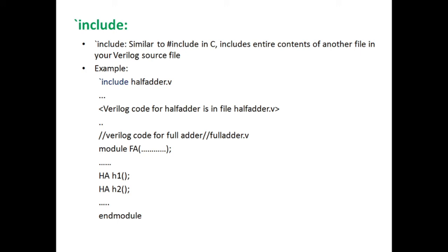Similarly, `include plays a vital role in our Verilog HDL. So I have used `include halfadder.v. Suppose I am going to design module full adder, with a, b, c, s, cout as its ports. The full adder is constructed by instantiating two half adders, HA, one copy is H1 and the second copy is H2. So this HA definition should be present in your Verilog HDL program.